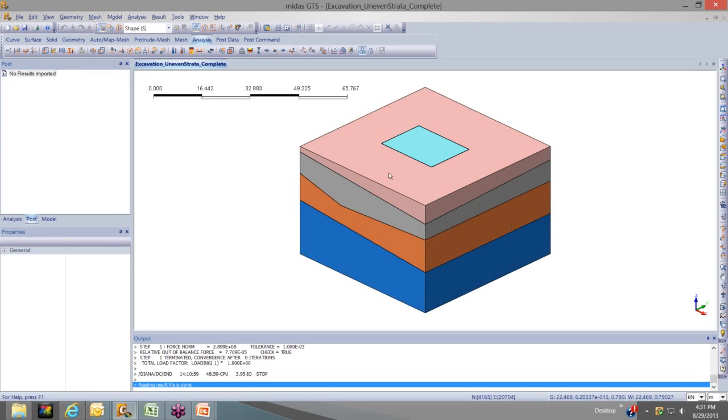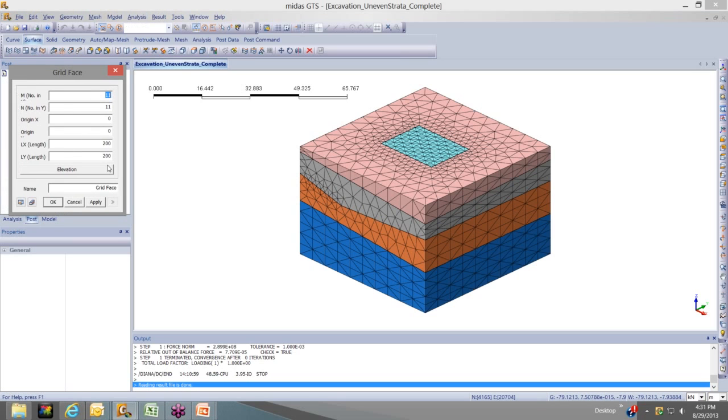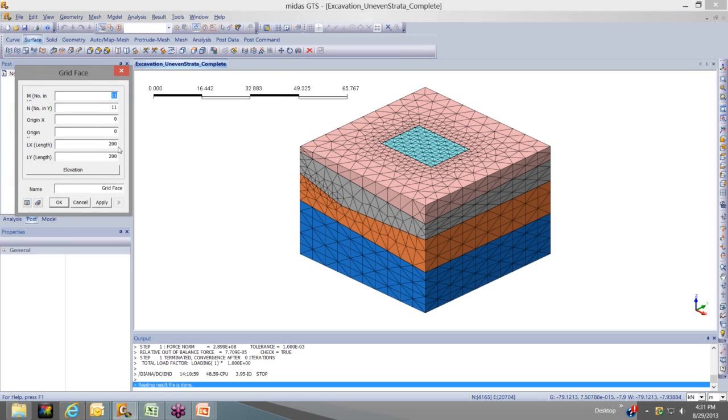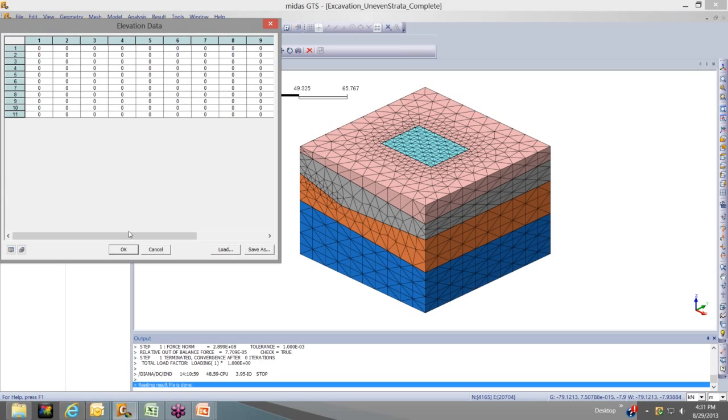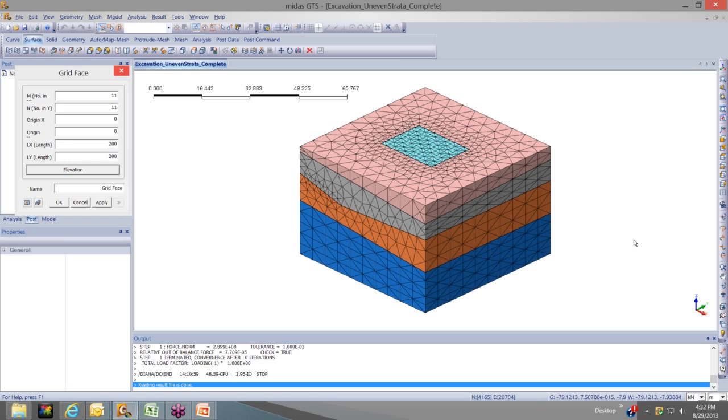And as far as the contours, once again, go to the surface. If I want to import an elevation surface, for example, an 11 by 11, I think, yeah. So if I had maybe a terrain geometry modeler or a contour modeler, I could just import the spreadsheet directly here, and you should be able to have all the exact coordinates. It's just a matter of specifying your coordinates correctly at that point.